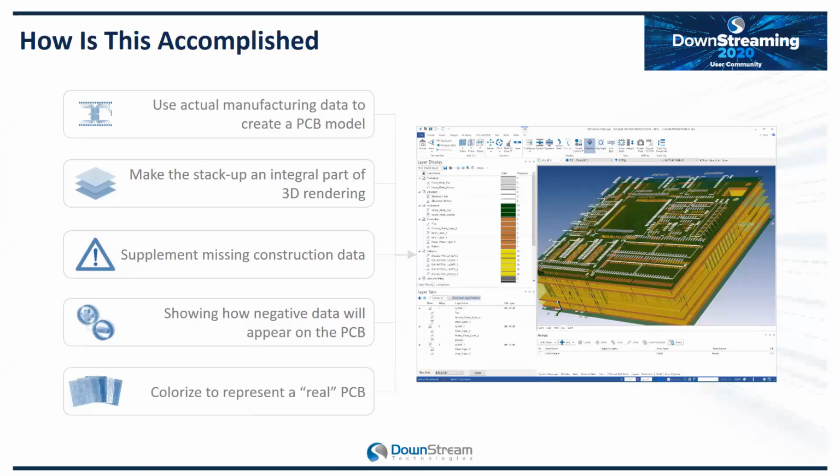Instead of using layer tables, we make the stack up of the PCB more of an integral part of the 3D rendering. This allows us to implement missing data that typically isn't found in your Gerber information, like dielectrics or prepregs and so forth. We show how that negative data will appear in the actual PCB by rendering it in a positive. And we can colorize the PCB to look more like a natural PCB as opposed to a CAD design.